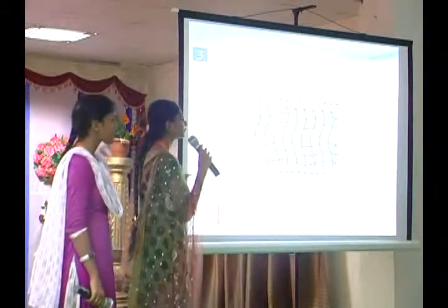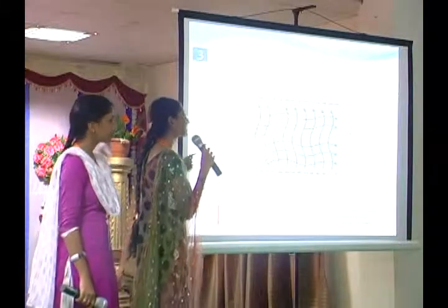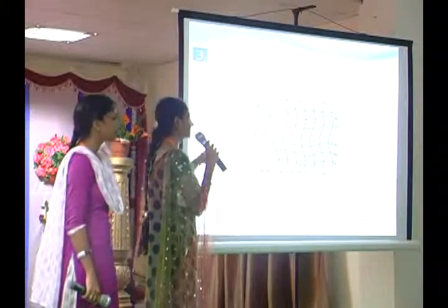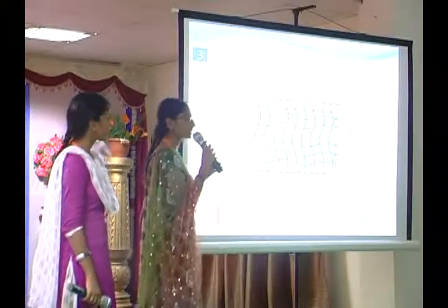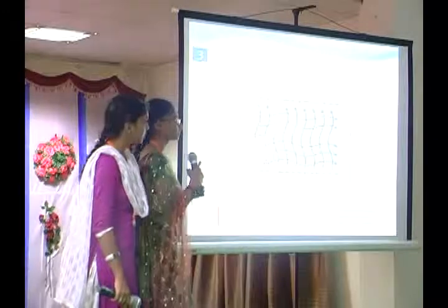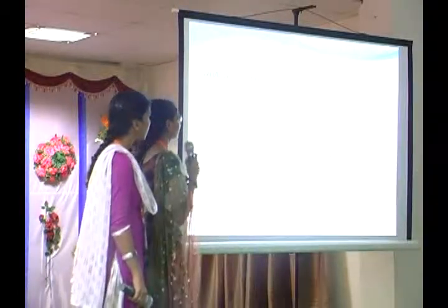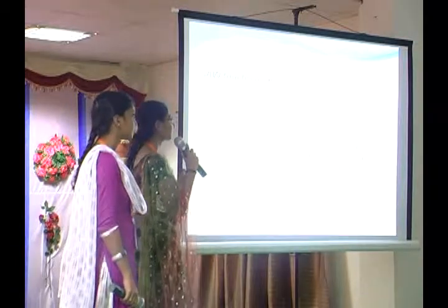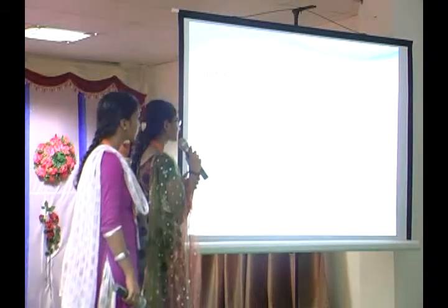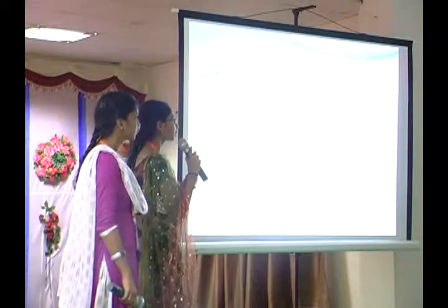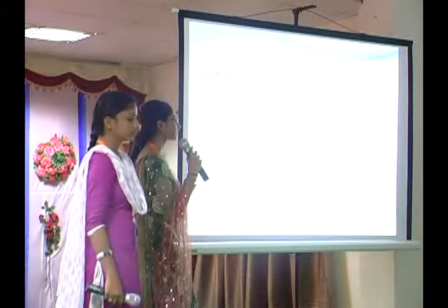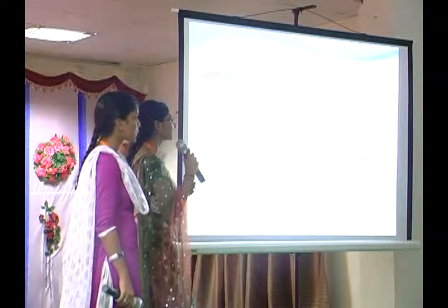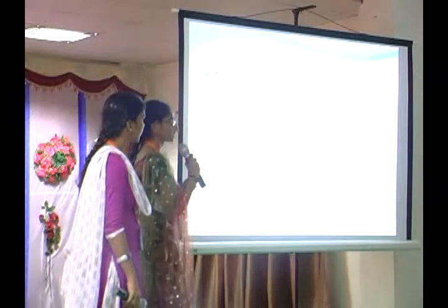See, this is the preview of a SAW touchscreen. If we touch a particular place, we can observe it is very visible in this type of touchscreen. There is a wave traveling across this, around the tip. Next. The characteristics of the touchscreen: it is a durable glass construction. It has very high optical clarity. It can be activated by a finger or a soft tip, but it is not completely sealable. It can be easily affected by a large amount of dirt and surface contaminants.